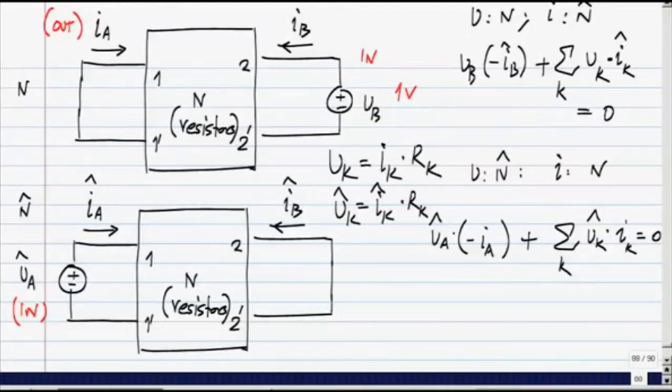It will of course be proportional because it's a resistive network, but that's not what this is saying, right? What is the final result we got? I_A by V_B is I_B hat by V_A hat, isn't it? It's a very interesting result. If you have resistors alone, this is known as the reciprocity theorem. The network is reciprocal. That is, if you apply some stimulus here, measure the effect there, and if you apply a stimulus on the other side, measure the effect here, they will be exactly the same. That is, the ratio of the response to stimulus will be the same. So, please understand this theorem carefully.